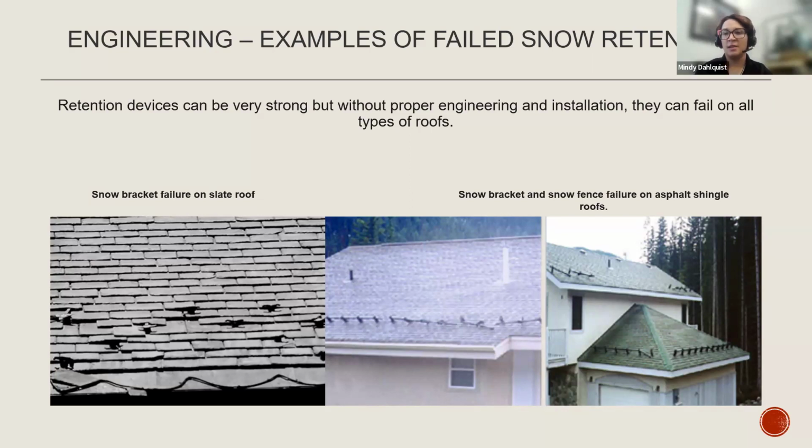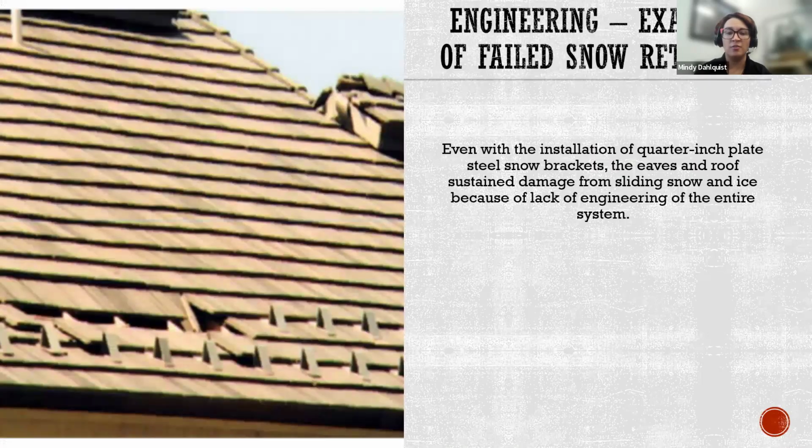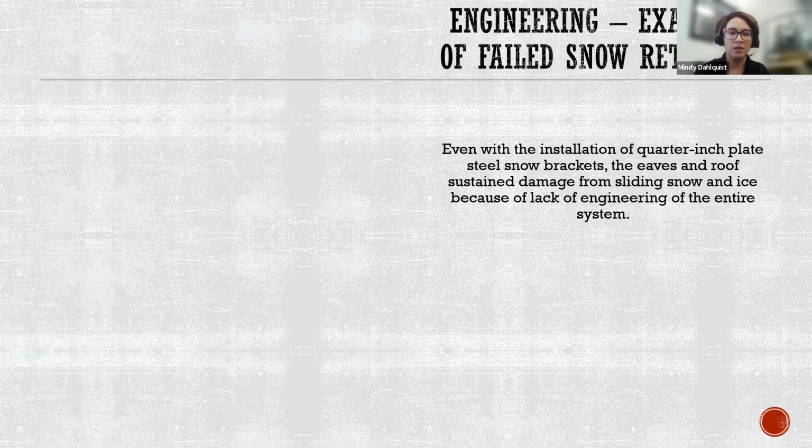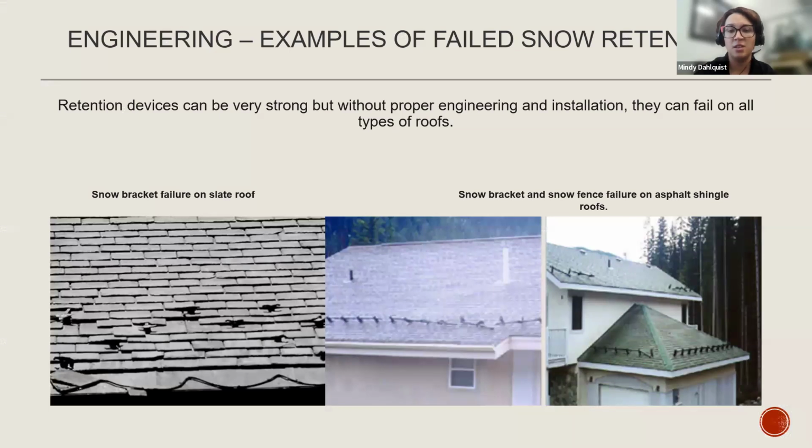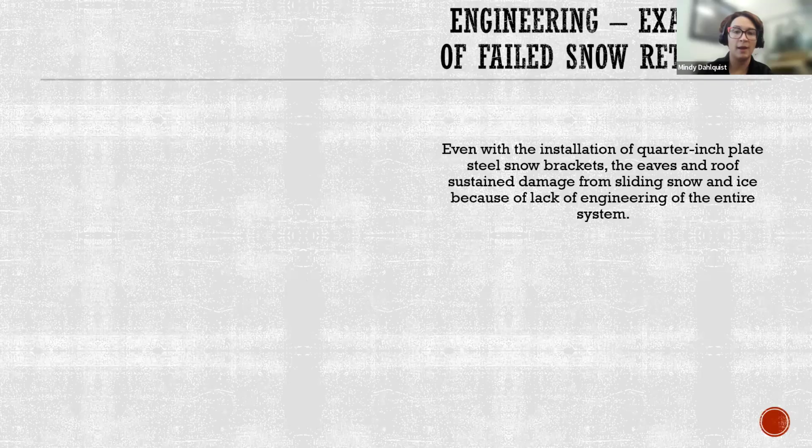One of our biggest design rules in snow retention for us is not allowing for stops throughout the field. So you cannot terminate the snow fences mid-field. That far right is the perfect example of that. You can see all of those fences have failed completely because that run did not continue. It may have also needed multiple rows, but the snow sliding into those areas is frozen into one mass and can just push those fences out of the way.